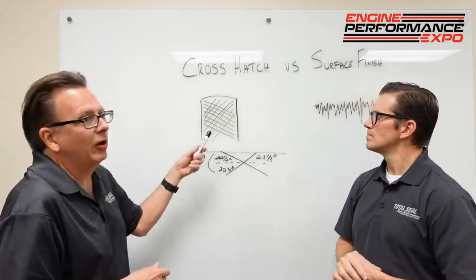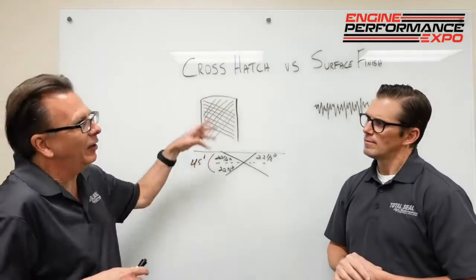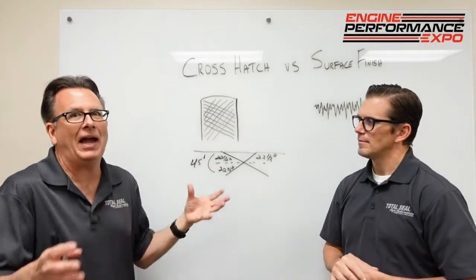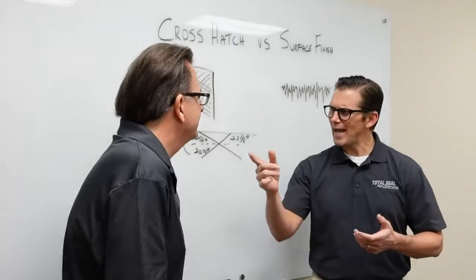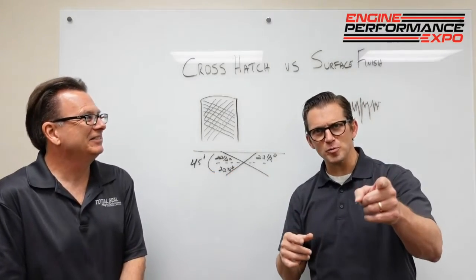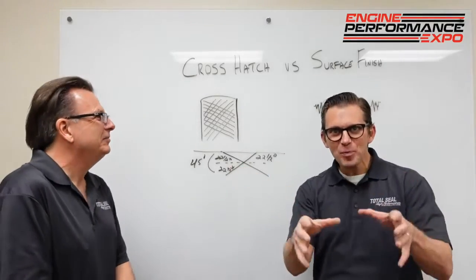So it's important to know what you're doing, what's the RPM range, length of the bore. We've got to help determine that crosshatch angle to go with that cylinder finish and just bring that package to the best that it can be. Package? It's a package. Sounds like it might be ring seal soup. It's a combination. It's soup, not steak.